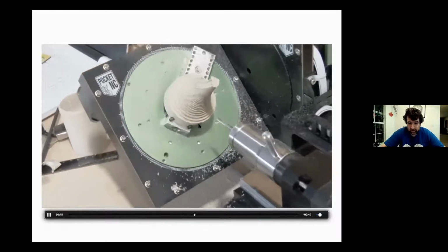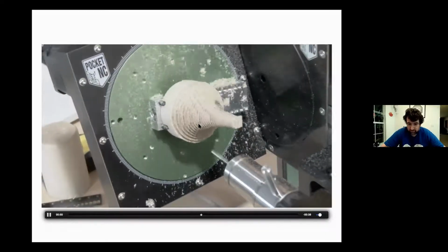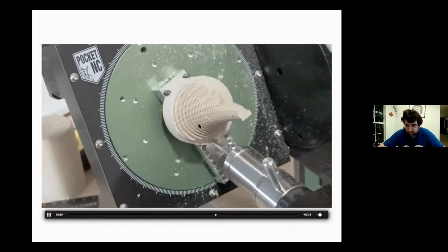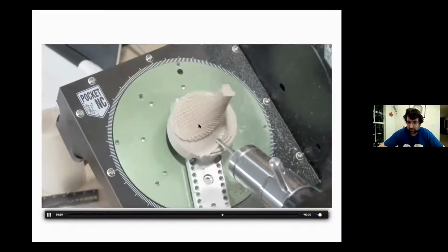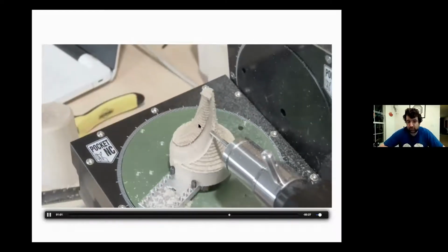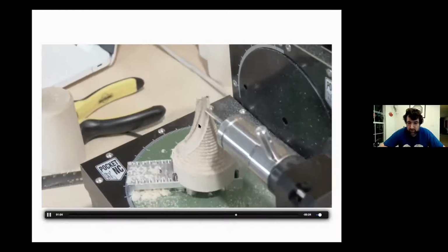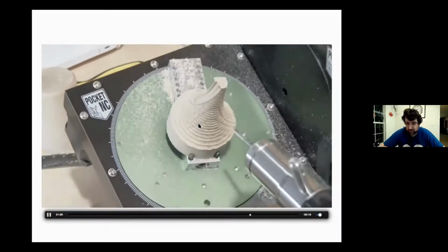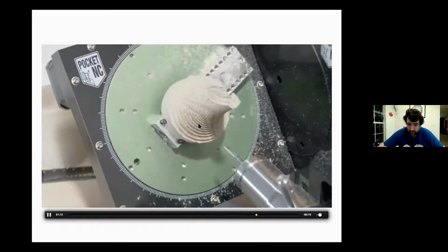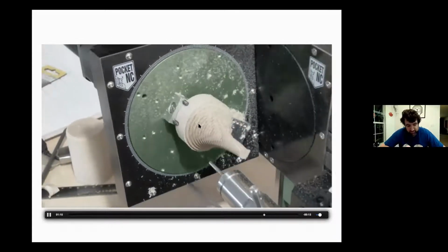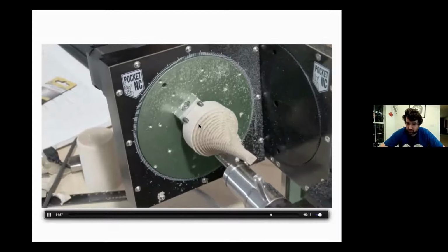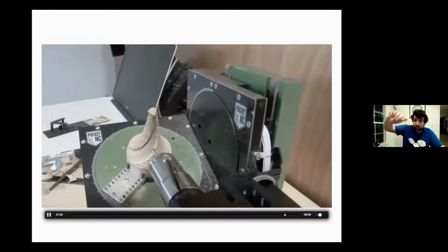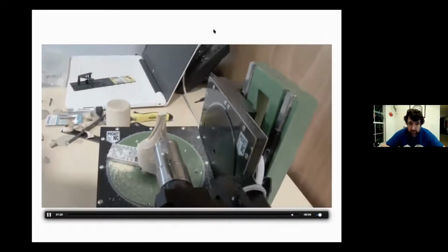But what we're doing here is actually, we're carving this surface, it's called a pseudosphere, and we're carving it with paths that are really designed for the geometry of the surface. And so you can see that the step over, the distance from one of these paths it's cutting to the next one is actually pretty big. So at the base, it is stepping over 3/4 of the width of the tool. And so the overlap between one path being cut and the next is quite small.